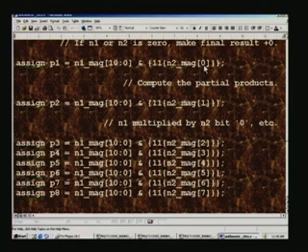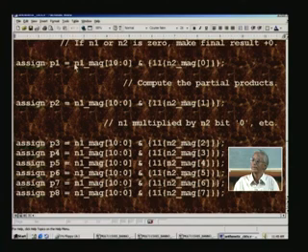If we inspect that particular bit and it is a 0, the partial product will have all bits 0, pertaining to P1, which is nothing other than n1. And if it is 1, the partial product will be the same as n1. Whatever the n1 number is, you will get exactly the same thing. So in one case it will be all zeros, in the other case it will be the duplication of this number. So either this number is got or a 0 is got.